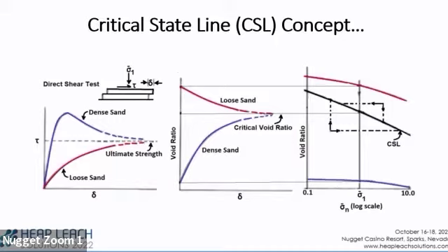But that's what causes liquefaction. So you need relatively loose material. You need relatively high saturation, not 100%. That's a common misperception, but it needs to be reasonably high. And you need a load applied, some sort of differential load.